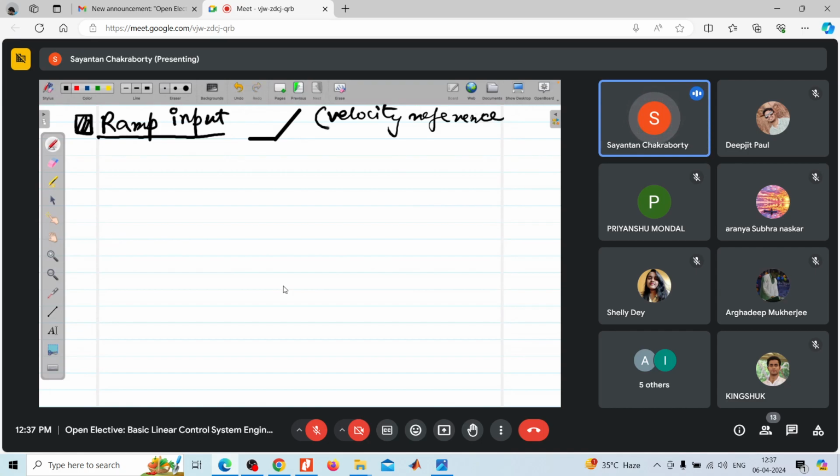See, because in our scenario, since it's a position control scheme, the only reference input that you can give is the position demand, right? You cannot give a velocity demand. So how do you represent a velocity demand in terms of position? A ramp signal in a position command will represent a constant velocity, right? So this is defined as Rs is equal to 1 by S square.